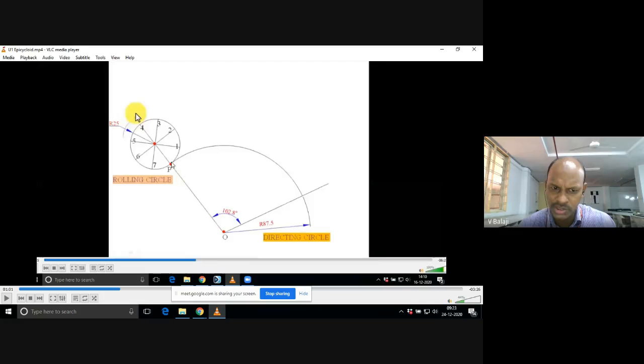So what you have to do is keep the protractor again. This is the starting zero line; assume OP is the zero line. So mark 11.6, 11.6, 11.6, 11.6, up to the last end of the circular path. So you will get 8 equal parts. That means you have divided the circular sector into 8 equal parts.